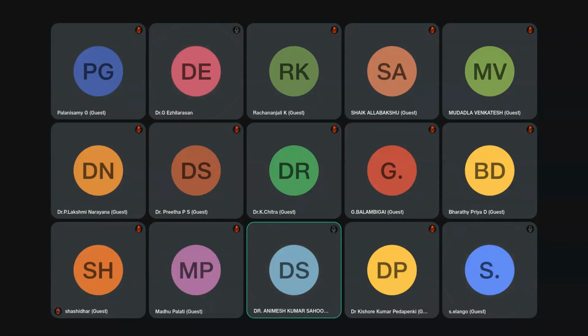When we say decentralized, mostly we don't use any kind of communication or some kind of low bandwidth communication. Now, when you say microgrid control, we may mostly follow the hierarchical level of control. One is the primary control, secondary control, and tertiary control.